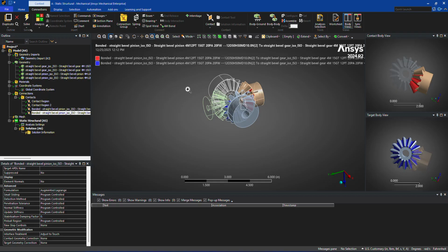Okay, the contact part is almost done. Now there is another part to add, which is the joint load, because without the joint load conditions or constraints, you will not be able to rotate something in static structural. Rotating something is according to time, and thus it actually needs transient simulations, but those are much more complicated than we think. So we have to stick to the static structural option, but we need a special condition called joint constraints. Now I will show you how to apply those.